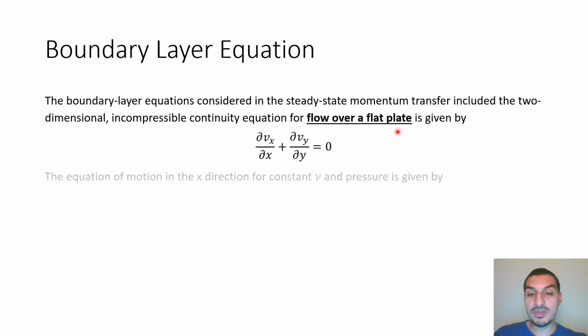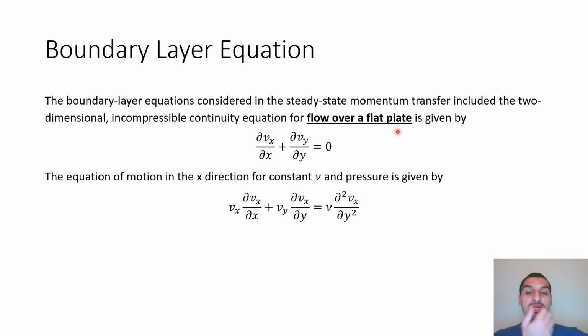This is the continuity equation, and this is the equation of motion, which are the mass balance and energy balance. This equation of motion is the general form of the equation. This is simplified, of course, but the general form of the equation of motion is the energy conservation equation. So this is mass balance and energy balance for fluid flow. And by the way, this equation of motion is the general form from which the Bernoulli equation was produced as a special case. So these are the two equations that describe the fluid flow over a flat plate.